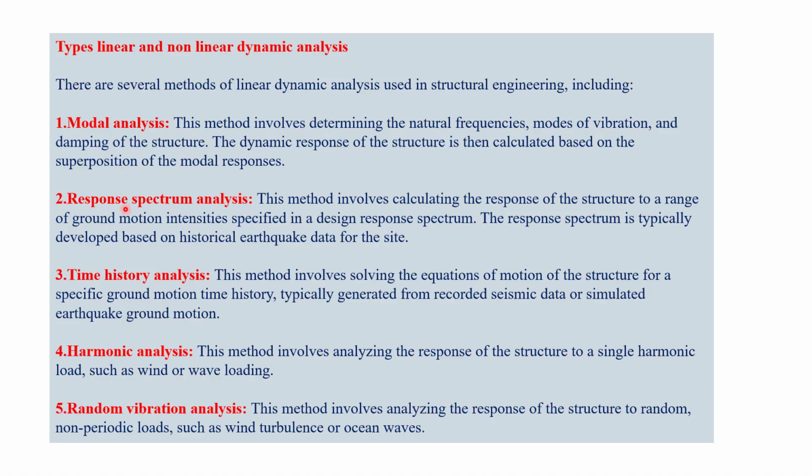The response spectrum analysis, where we just extract the range of ground motion. Then we define this particular response spectrum, and depending upon that we try to deal with the structure and try to increase its performance. We'll have the graph, and from that data we'll see whether it is failing or not and whether it is under limit, and then we'll try to deal with that component.